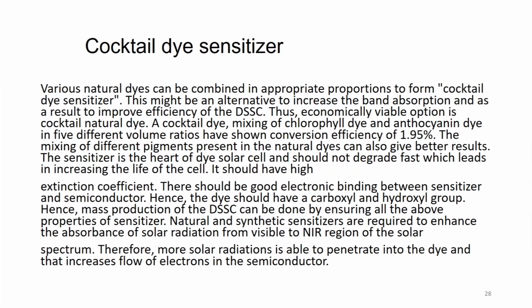Even cocktail dye sensitizers have been used. What does the word cocktail mean? A mixture of more than one or two dyes. Various natural dyes can be combined in appropriate proportion to form cocktail dye sensitizers. This might be an alternative to increase the band absorption and as a result improve the efficiency of dye sensitized solar cells. Thus, an economically viable option is cocktail natural dye.